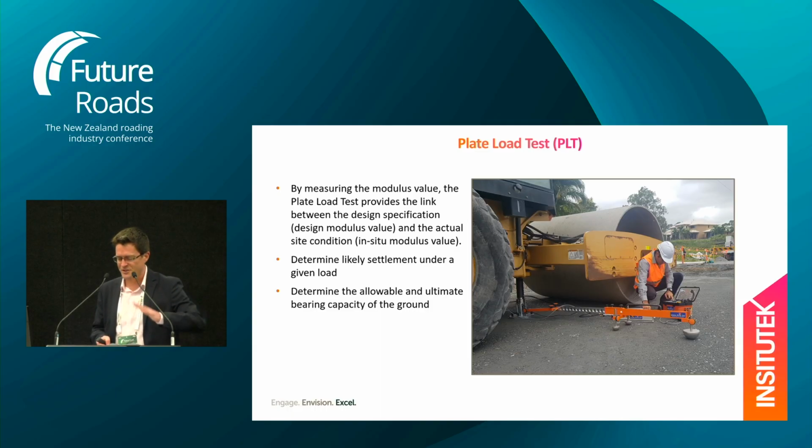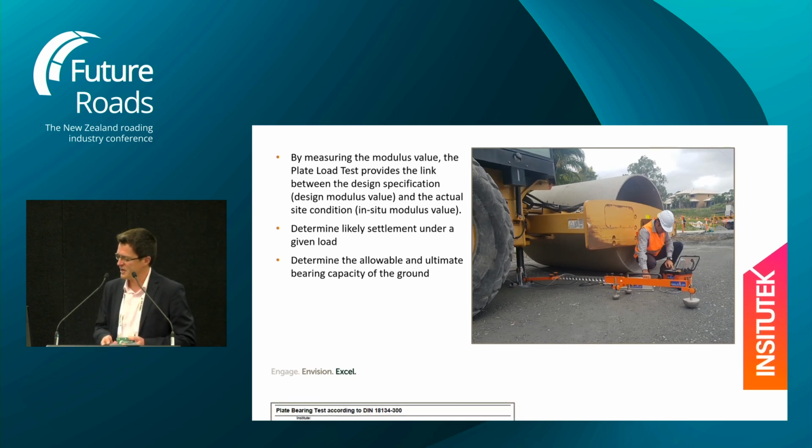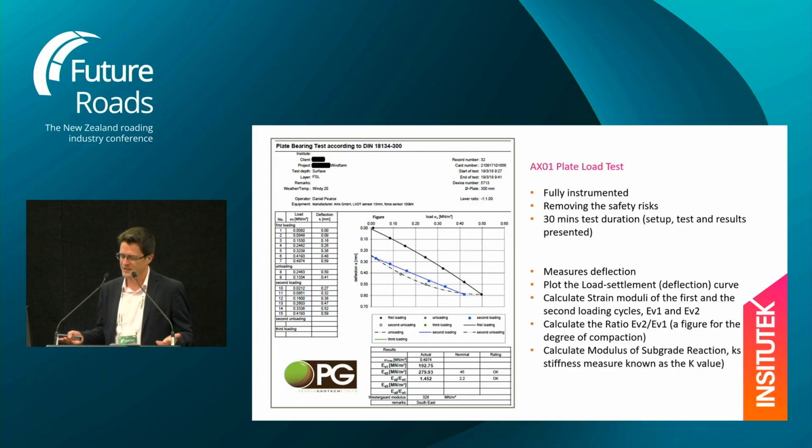We're jacking against it, pushing a plate into the ground in increments, and measuring deflection. The idea is that we come up with a graph from two loadings: we load, unload, and reload. This gives us an indication of the modulus, so EV1, EV2, if that's familiar terminology to you, and the ratio between these.